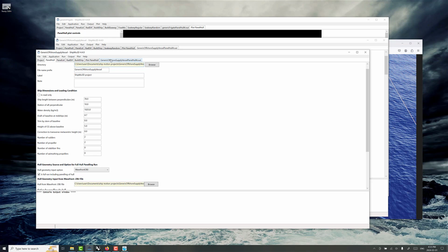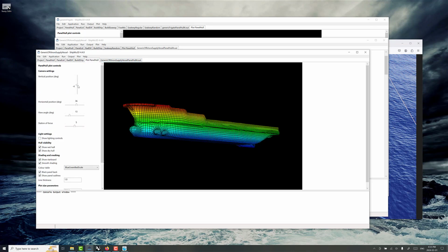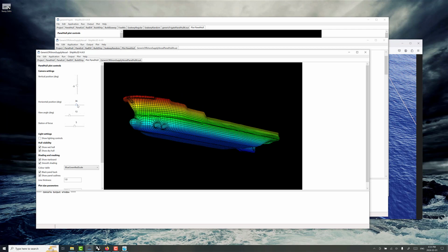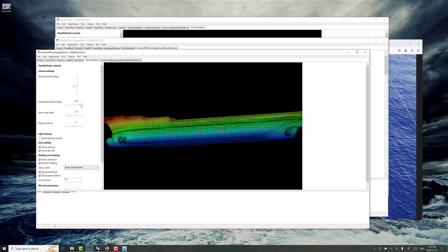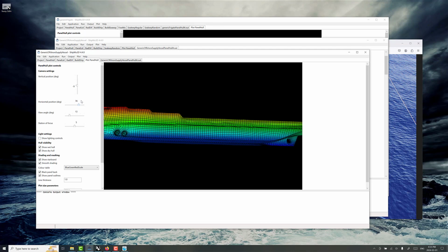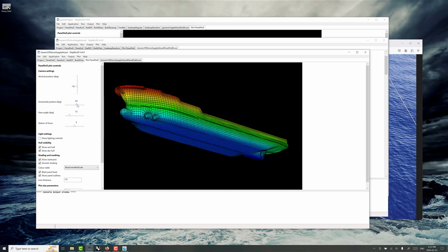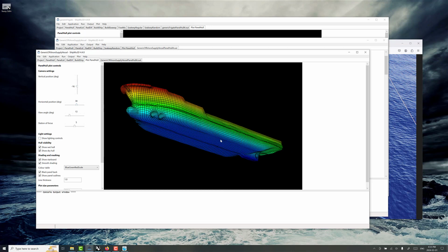And if we look at a more realistic view of offshore supply vessels, they may have multiple bow thrusters, including one in the back as well, where you might want to see what those gaps do to the hydrodynamics. So of course, you've got to mesh those, and then the detail can add up. Maybe you don't want a simplified mesh in the mid region. Again, this is around 80 meters length, 16-meter beam or so.